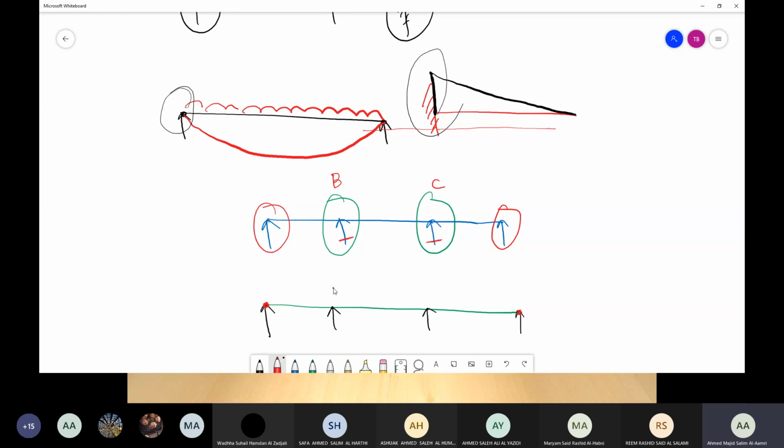We are going to draw a small cantilever here, representing this continuity, and then once again a small cantilever on the left and a small cantilever on the right, since it's continuous from both sides. And then when we draw the bending moment diagram, it will go in this way. Are we clear about our bending moment diagram and how to draw it? Yes, mister.